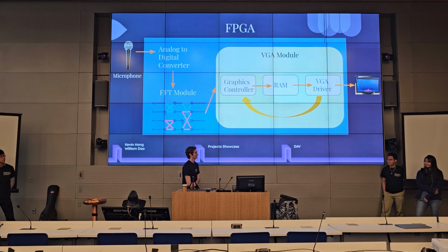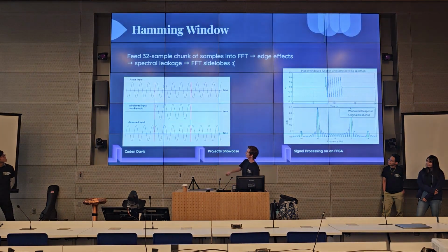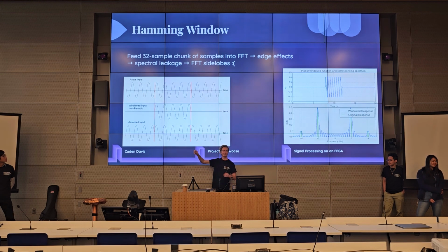Thank you. Of course. But yeah, and to go into the FFT, first, FPGAs, it's a microcontroller, but really annoying. But the trade-off is getting to do something super specialized, which is often really good for some of these signal processing operations. Signal in this case is the audio going into a microphone. And when we say we're taking the FFT or converting to frequency domain, I have a picture right here. This is basically decomposing our signal into these representative sine waves. A sine wave just being a very neat up and down squiggle.